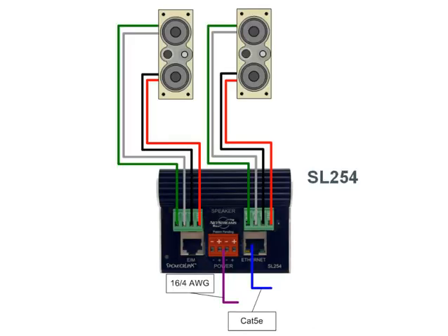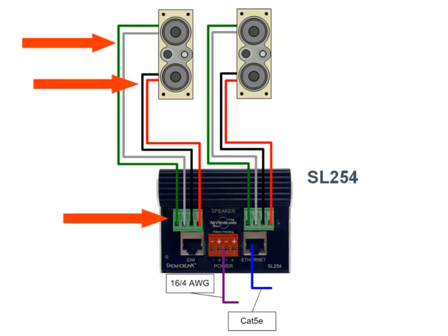Cabling the SL254 is a bit different when you're connecting IP-ready speakers. You'll need to wire the tweeter and the woofer on each speaker. You can see that the 2 pairs from each speaker connect to a 4-pin modular connector that drives that specific speaker. This allows the speaker links to drive the speaker's tweeter and woofer as a single speaker.